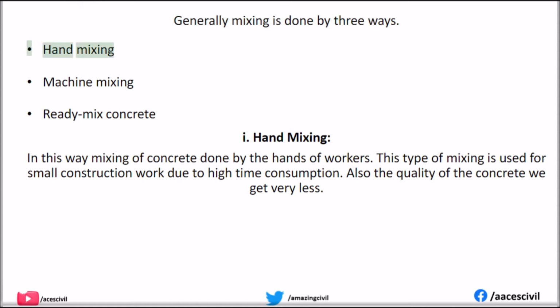Hand mixing, machine mixing, ready-mix concrete. Hand mixing. In this way, mixing of concrete is done by the hands of workers. This type of mixing is used for small construction work due to high time consumption. Also, the quality of the concrete we get is very low.